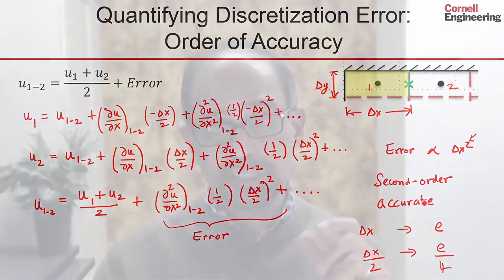But the second order accuracy has a disadvantage in that the iterations are less prone to converge, that is, it's less stable compared to the first order. So the advantage of the first order is that it's more stable, that you can drive the linearization error below the tolerance more easily as you go to more complex problems. And we will see these relative advantages and disadvantages of the first order and second order schemes when we get into the ANSYS Fluent solver.